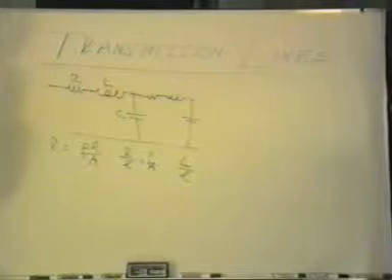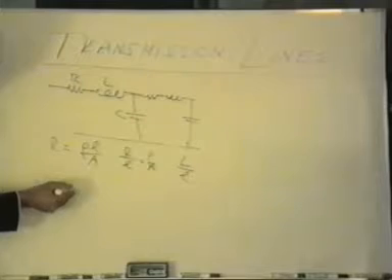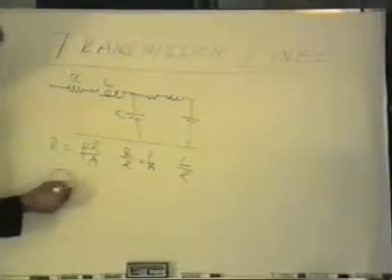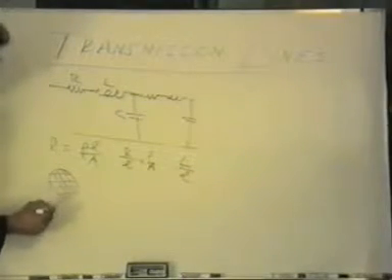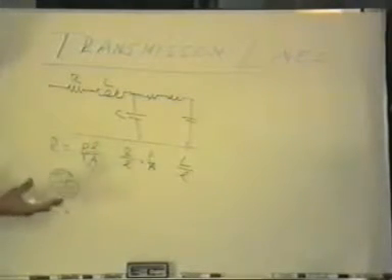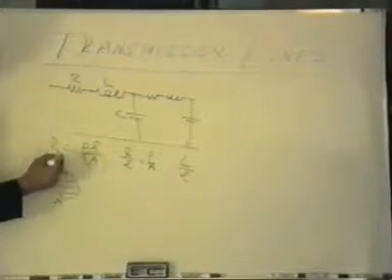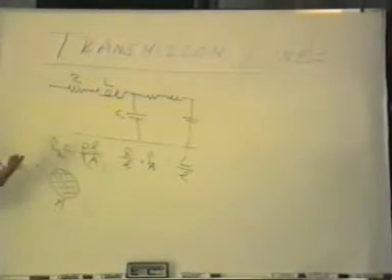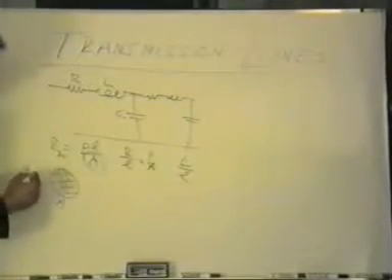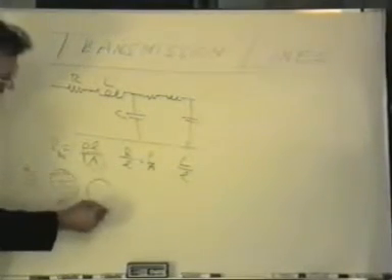Let's talk about resistance just a minute. We'll talk about inductance and capacitance later. In the case of resistance, we're very accustomed to seeing a circular cross-section conductor which has a cross-section area A. This is the A that appears in this equation. And at DC, it's a fairly simple thing to calculate the resistance per unit length or the overall resistance of a piece of conductor. However, at AC, it becomes a bit more challenging because the phenomenon observed is this.